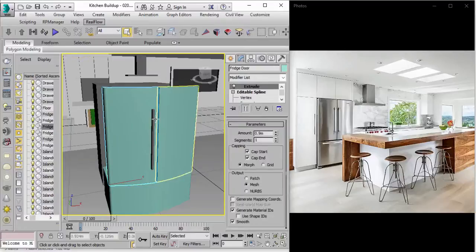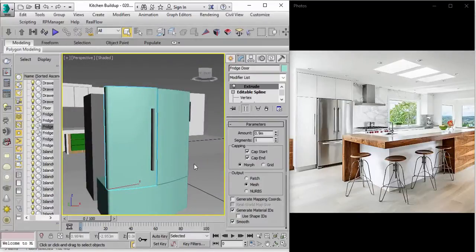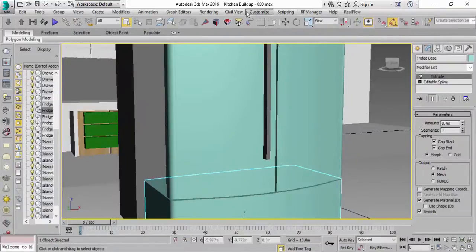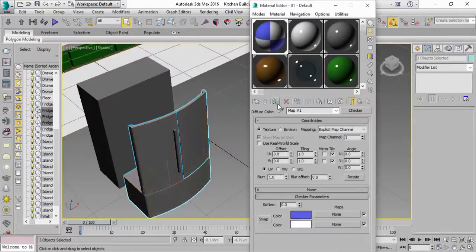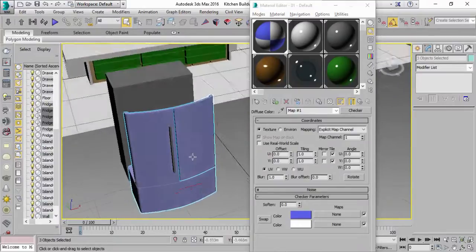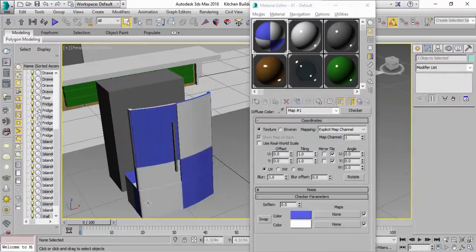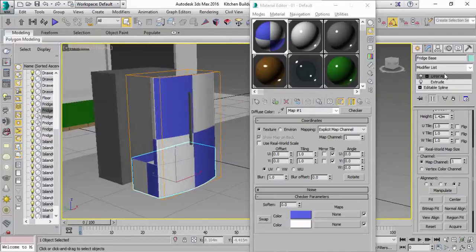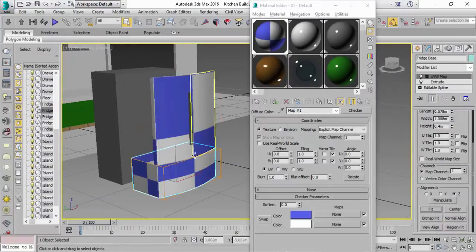Then, after we've done that, because we know this is definitely the final look of the fridge doors, let's go ahead, and especially this one, the base, please go ahead and apply the checkered material to it. So rendering, material editor, compact material editor. Please select all these objects here, including the doors. Assign them this checkerboard texture and show them in the viewport. And right away, let's add a UVW map to all of them. Make them boxes. Then this one here, we're going to make it fit. First make it unique, sorry about that. And then while it's a box, make it fit.